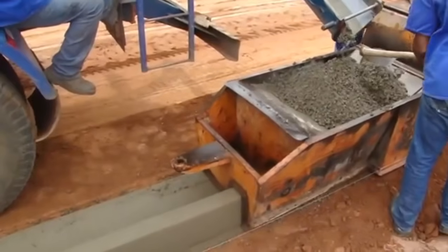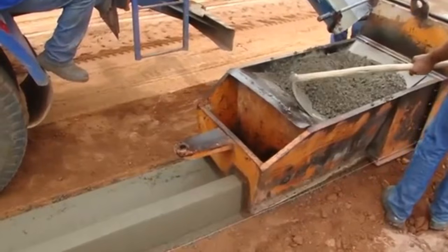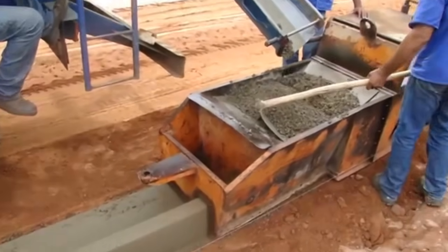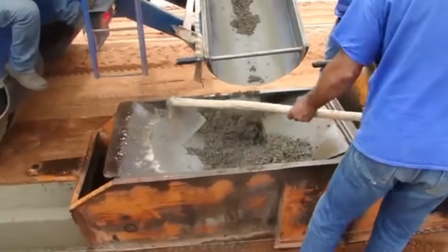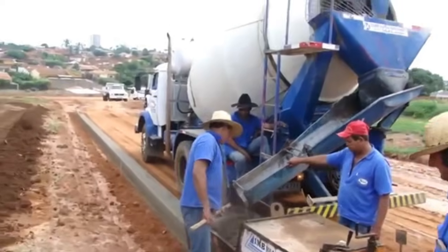The next item of work is Curbstone. The Curbstone provides a clear physical and visual marking and delineation. It makes the drivers conscious of the pavements and greenery areas in demarcating roads, streets, car parks, etc. It makes a clear-cut view of the carriageway. It helps in preventing any kind of spreading from the carriageway.